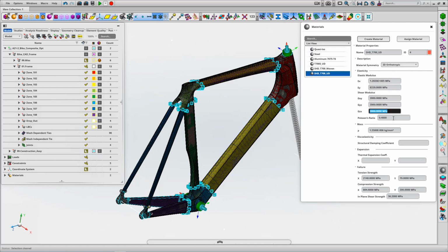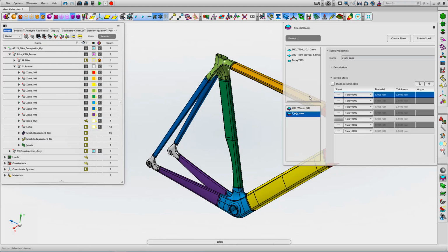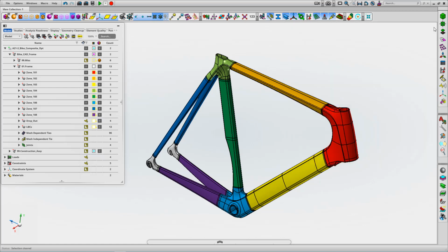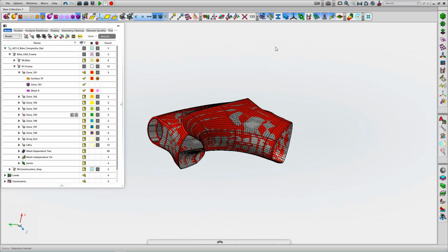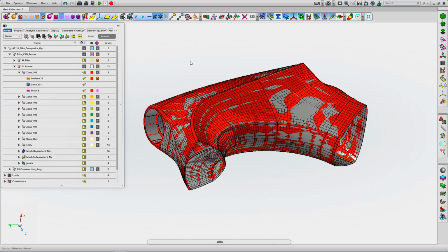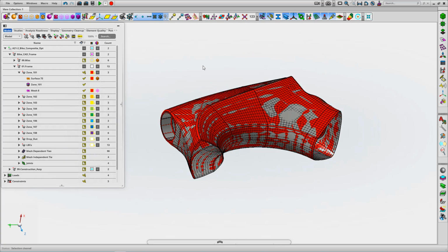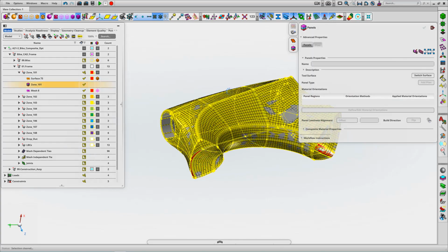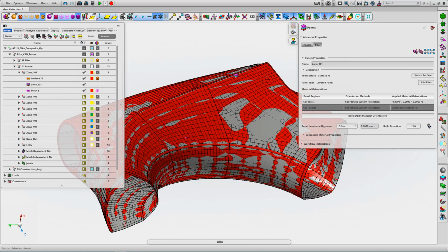So we've got a UD fabric system set, so we've got things like the stiffness and strength, or the modulus and allowable strengths defined in there, and we can show those for a woven fabric as well. So we're specifying our material definition. Once we've got those material behaviors set, we can start to build up our laminate stacking sequence for a typical build. And then we've got those set, we can then apply those laminate behaviors, or that laminate stacking sequence, to the zone of interest.